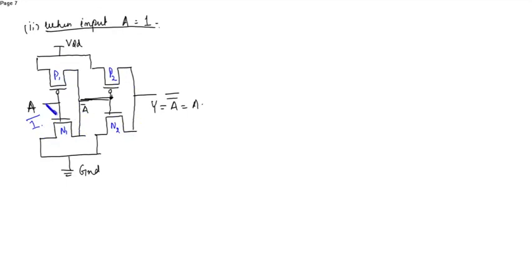When A is equal to 1, N1 will turn on and P1 will turn off. P1 gets open circuited, and N1 gets short circuited.